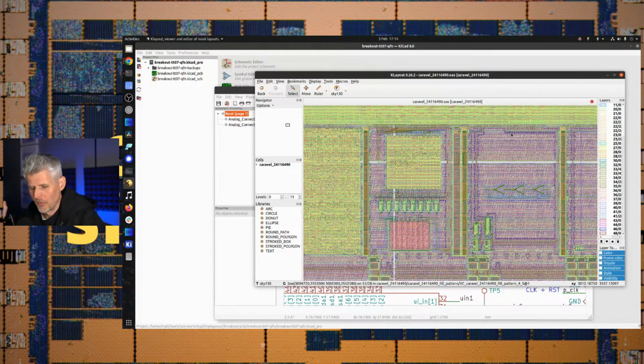If we've got like a 1 volt output, then maybe that's not going to be enough to swing the 1.8 volt mux or buffer in the multiplexer side. And the same thing, if we're supplying it with a 1 volt core, and then we've got a 1.8 volt coming in from the outside world, that could also be dangerous. So we're not going to use any digital I/O. So we're going to put the digital block inside the analog part of Tiny Tapeout.